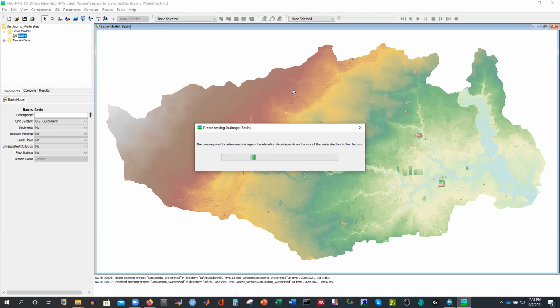So we have the option to create the mesh or grid in a future tutorial. Definitely I'll do that, but today I'm going to show you how to create the lumped model pretty quickly, because most of the time what I do is create that lumped model and calculate the basin average precipitation and basin average, other values we need. If we even use the evapotranspiration module, we need to calculate that.